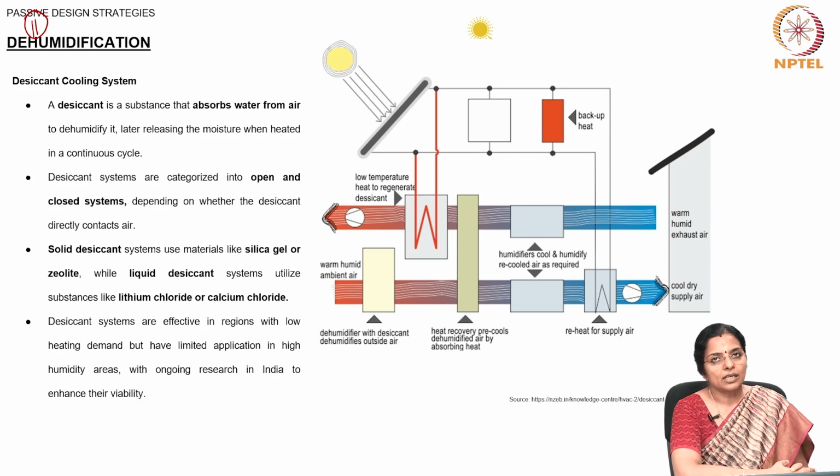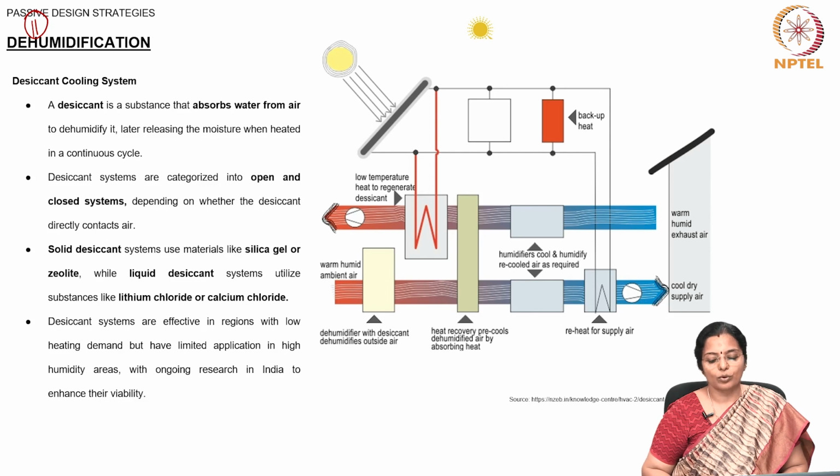Normally, if desiccants are used, then they are used in combination with the air conditioning system, because the act of removing moisture from the air by the desiccant is an exothermic reaction and it gives out heat, further increasing the temperature of the surrounding air.